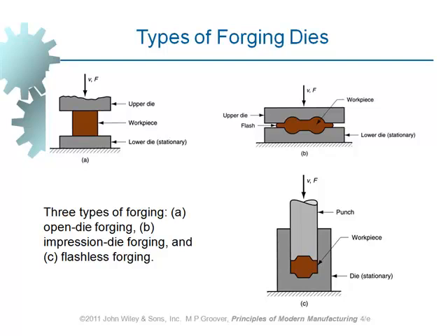Often, hot working forging operations are used in industry. And we've got 2 different types which are shown in this slide here. We've got open die forging like that one, when we've got 2 flat dies just like that, and we just subject the material to pressure, which could be of the impact type, just like that, or it could be compressive, just subjecting material to compression. Both of them are used and do improve the properties of the material.